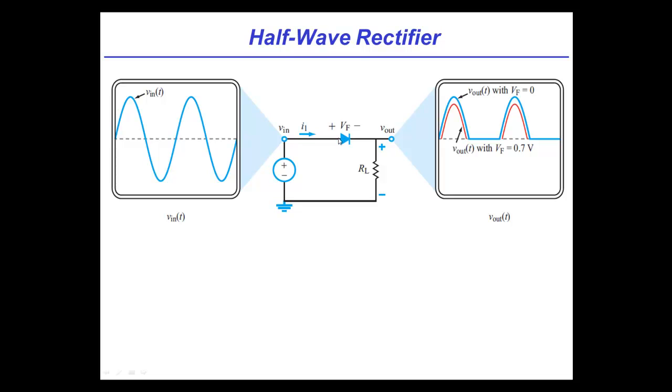Right. Got it. So what that means is when the voltage is positive, the current is positive, because there's a resistor here. You can just do KVL around it, and this positive voltage will give you a current going left to right. So positive voltage will give you positive current. That current will be fine with one little wrinkle. But when it wants to go the other way, it won't. It'll zero out. It's just like your bicycle.